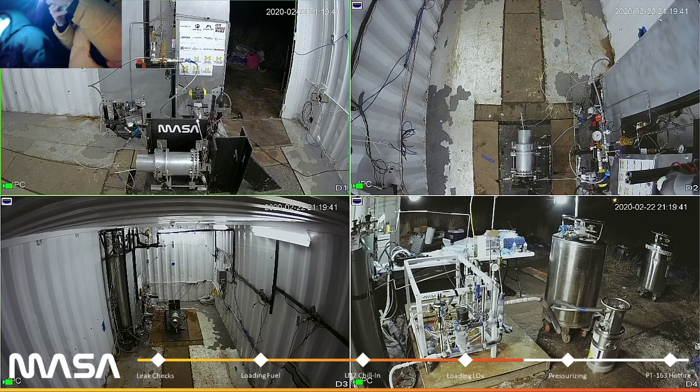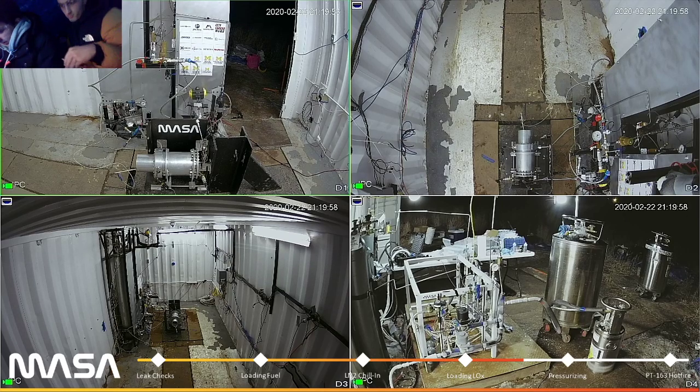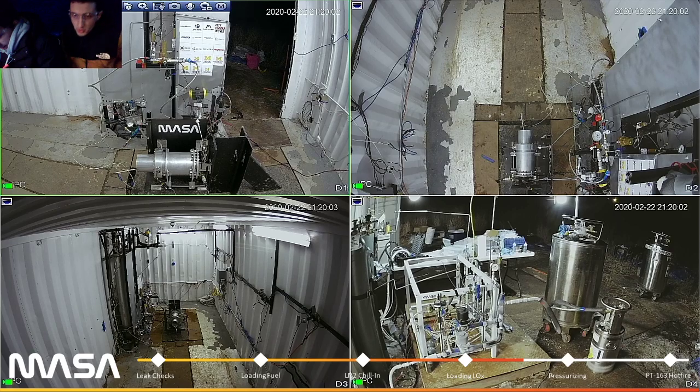The hot fire is 2 seconds because primarily we're testing the ground systems, the propellant tanks, the feeds, pressurization systems, propellant valves, engine controller. The engine itself is not really the main test here. We're really looking to see how much thrust we get, and the thrust measurement can be done very quickly. We only need a short burn for that. Mainly it's a demonstration of the entire system, not just the engine combustion chamber.